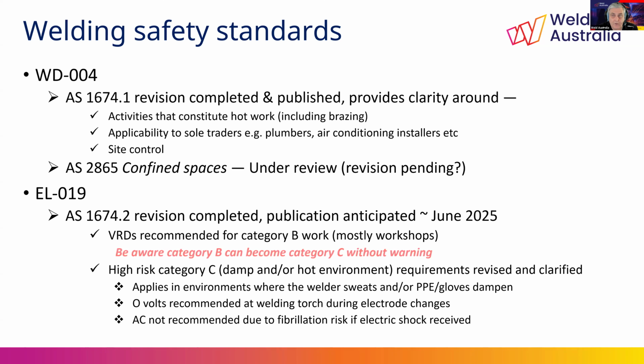But if you don't follow the weld procedure, the issue is going to be is the work that you're doing actually going to meet the requirements of the standard that the customer is asking for, and do you need to consider doing some testing to verify what you're actually producing.